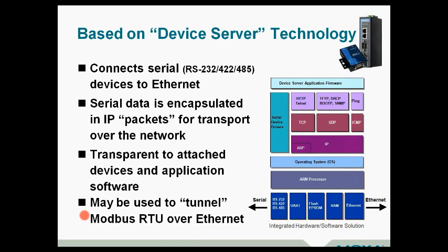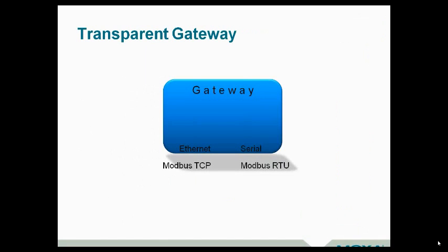There are some caveats with that. You can only do point-to-point connections. You're limited to one device and one master. There's also some caveats in terms of timing. You've got to be a little careful of setting this up because of the way Modbus works for an end of message, which is typically 3.5 character times. So if we're talking about 9,600 bits per second, that's about a millisecond per character. So at the end of that message, at 4 milliseconds, you've got to be able to stop that communication and let the master take over. So again, if you need help on that, let us know. We can show you how to do that. But it's certainly a challenge for a lot of folks, and not what everybody needs when they talk about Modbus TCP.